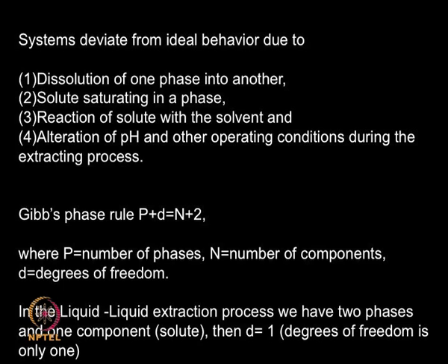Alteration of pH and other operating conditions during the extraction process: of course the pH is going to change, sometimes temperature may change, because when you take a cold solvent and use it to extract a solute from a hot fermentation broth. So these operating conditions also will affect my extraction process, so you will not have this type of thermodynamic equilibrium taking place. So you need to consider that in reality there is non-ideality, and the streams leaving the extractor are not in equilibrium.